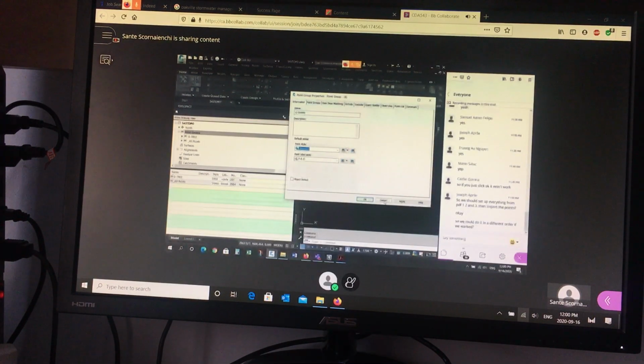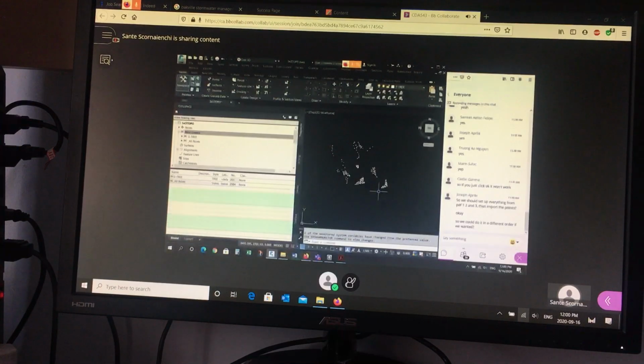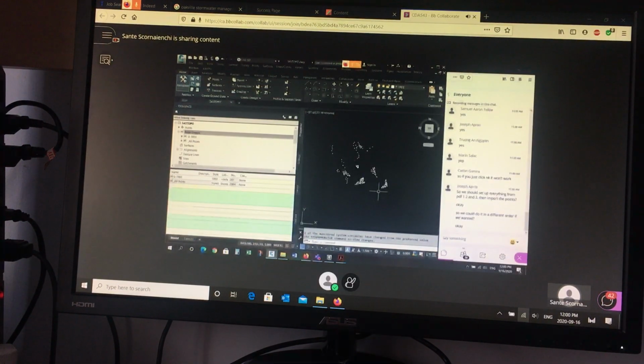Yeah, you could, but I don't recommend it. I would do them in order. Do all of the description key programming, do all of the point styles and point label styles, then create all of your groups and assign those styles. You can't assign them if they're not created. So I'm trying to give you best practice. Okay?